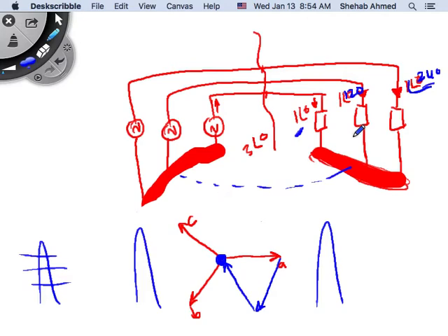Is there necessarily a lecture going on in the second room? Not necessarily. The room may be dark, there may be no consumption of load at all, right? So if the engineer designed it such that one of the phases of the three-phase system is coming into this room, and the other phase is coming to the other room, is there a balance between the two rooms? Are they seeing the same load? They're not going to be seeing the same load, so there will be an unbalance, right?